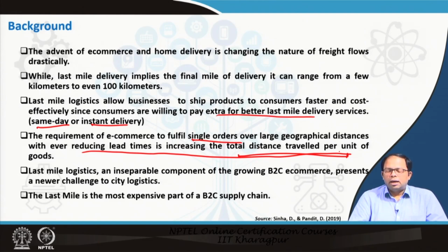But usually it's very difficult to track the trip chain of a person who is delivering like that, because we have to have a subcategory of those kinds of services, and then add those trip chains. So instead, it's better to model using a freight modeling framework and identify the people engaged in these activities. Then, based on the activities of those persons, we can identify what sort of trip chains they form, and that could be added into the overall travel demand generated in an urban area.